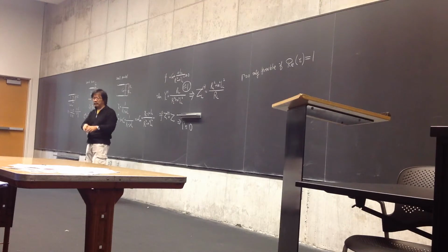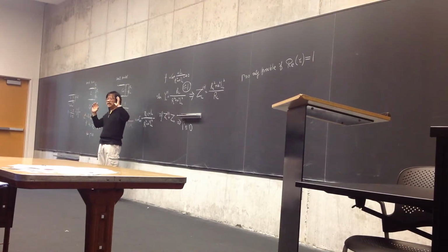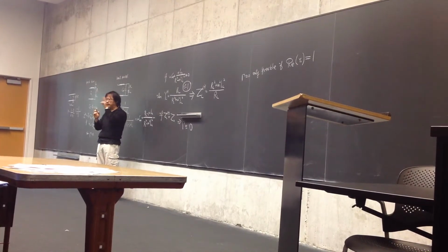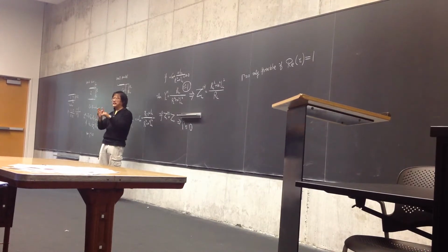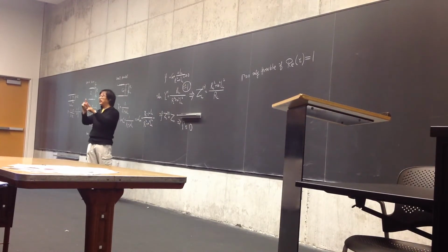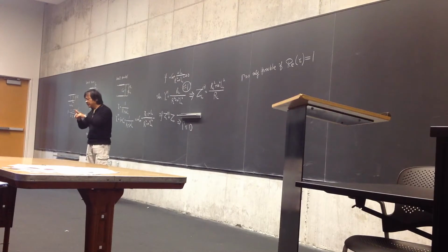So now, think about how can you do matching? When we say matching, that means gamma equal to 0. For gamma equal to 0, you need to have two conditions. One is the total admittance at a location must be a real number.